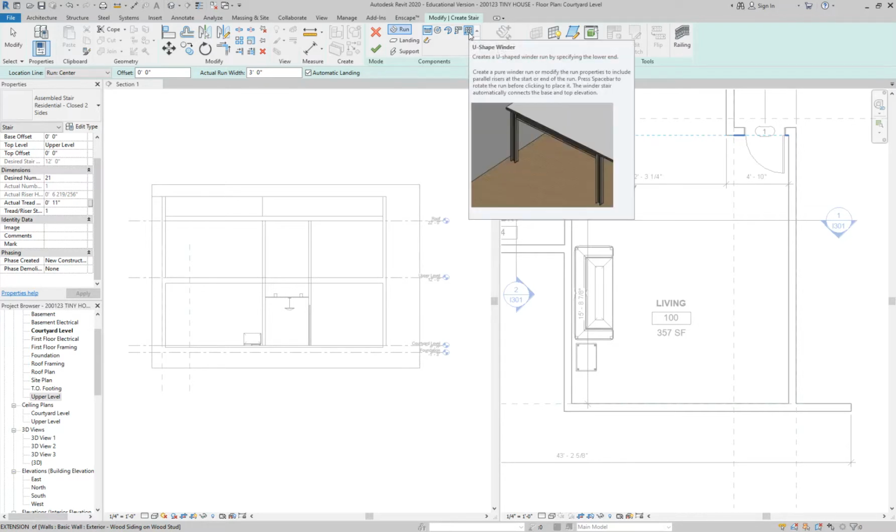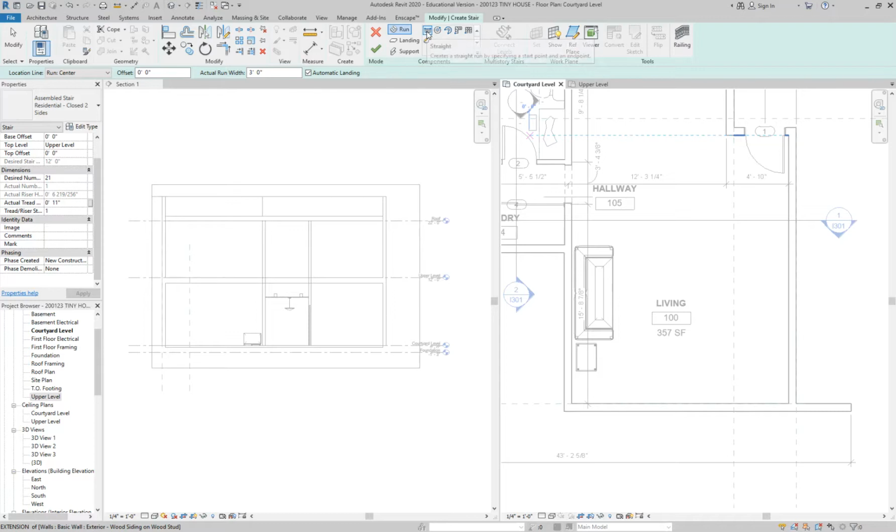Let me talk about the terminology of these for just a moment. So a straight stair can also turn. A straight stair can be straight like this, or you can add a landing and then have it turn basically in any direction. It just means that the stairs themselves are straight. Now the winder is different because what a winder does, I'm going to draw this in blue so I don't mess up the straight stair, those stairs actually start to wind. So the stairs themselves start to wind. So this will be the most common one we use, but you can also play with the different stair types.